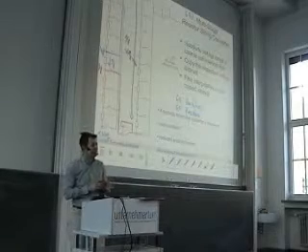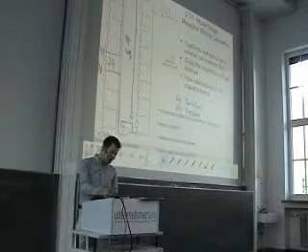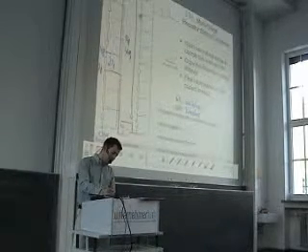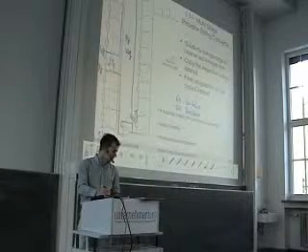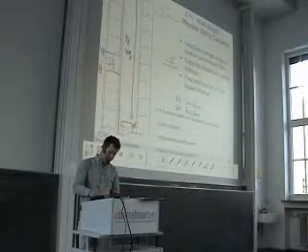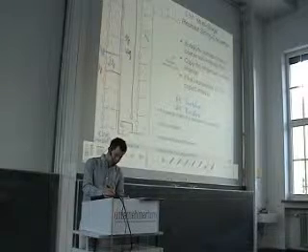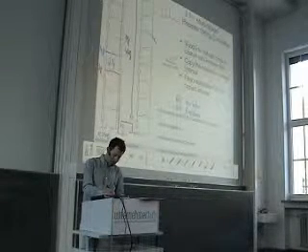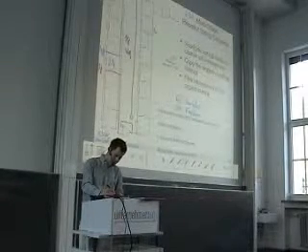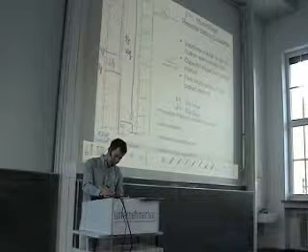And now we use a second resistor string. And this second resistor string subdivides this 1/8 times Vref again. Let's assume as an example that we close this switch and connect it to the output buffer.